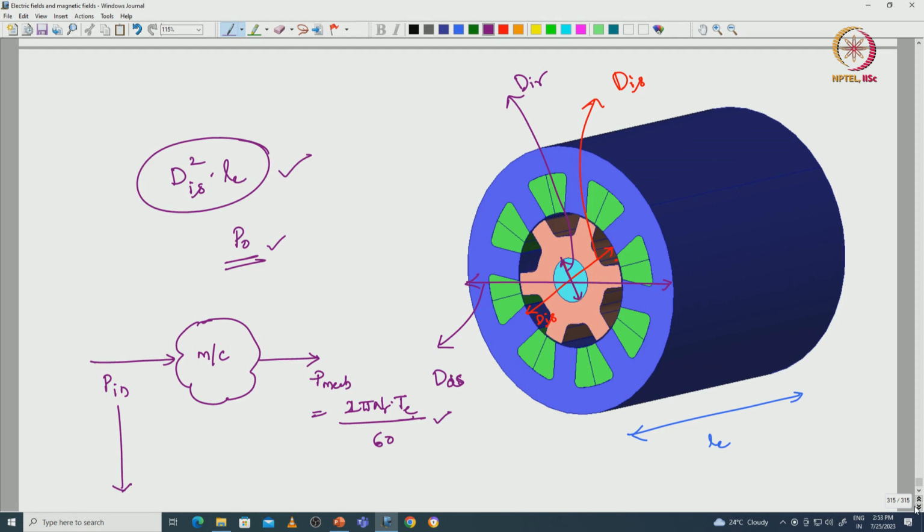It is not an AC machine in terms of power factor and phase, RMS voltages and other things. It is a type of machine where the excitation current pulse is defined with respect to the duty cycle, similar to the DC-DC converters or DC machines control, but it is not a type of DC machine.